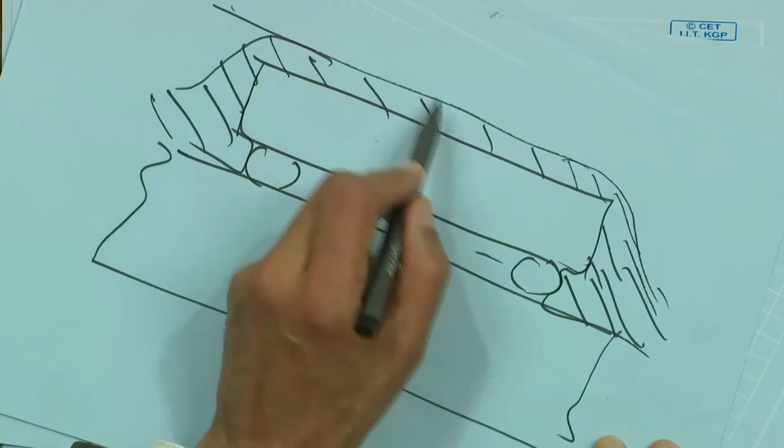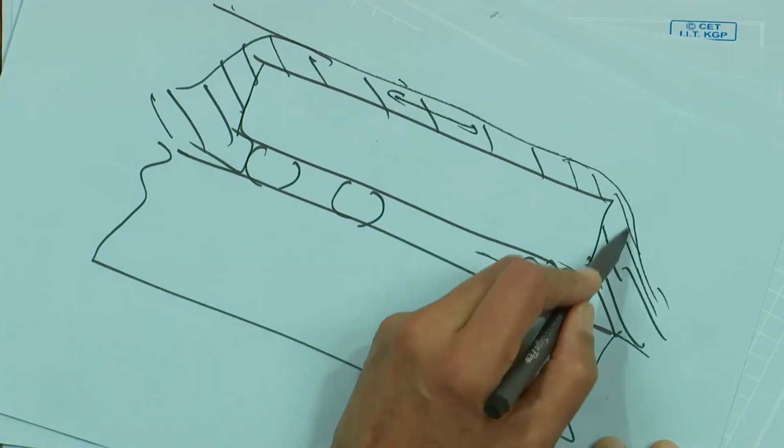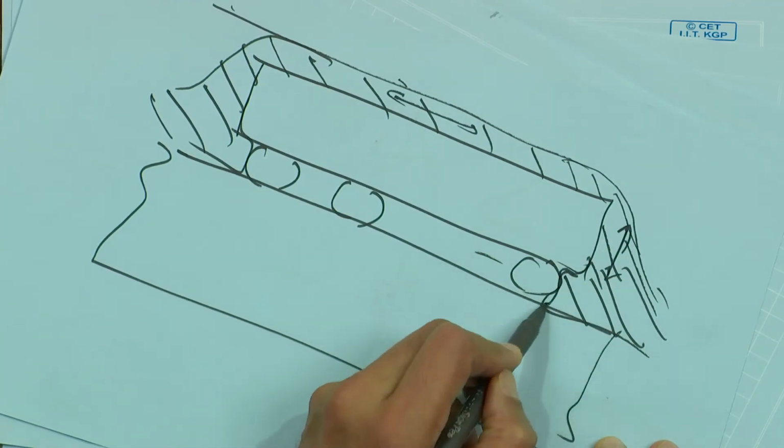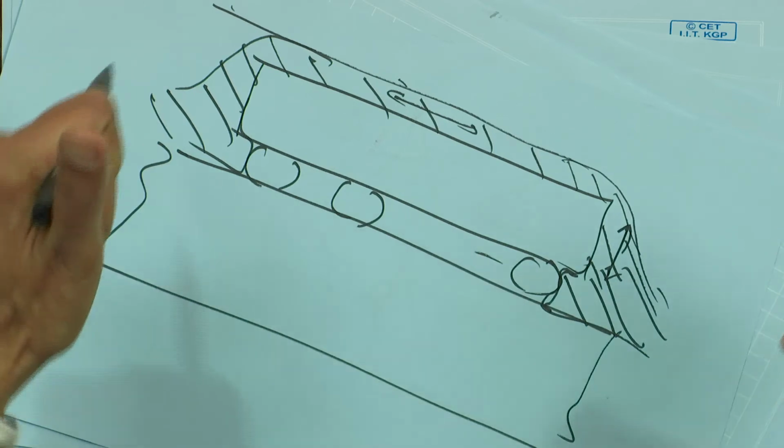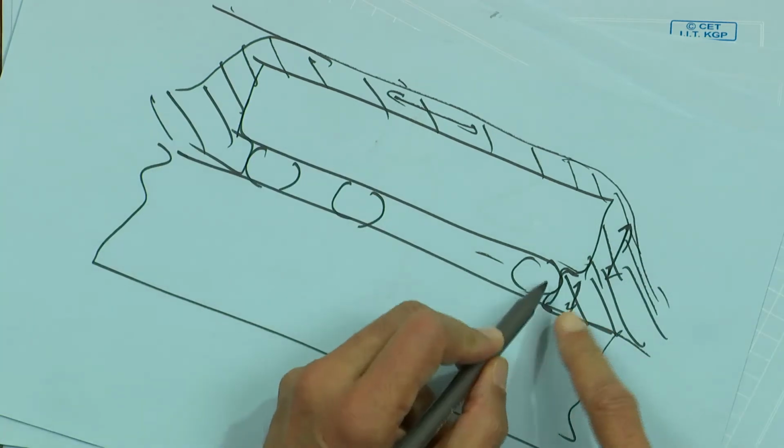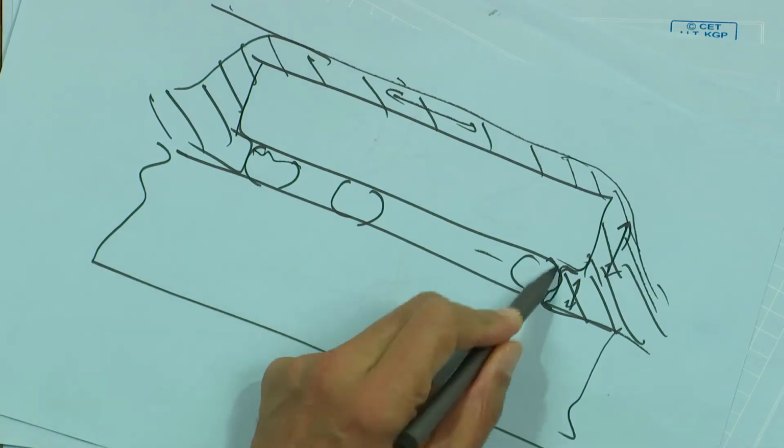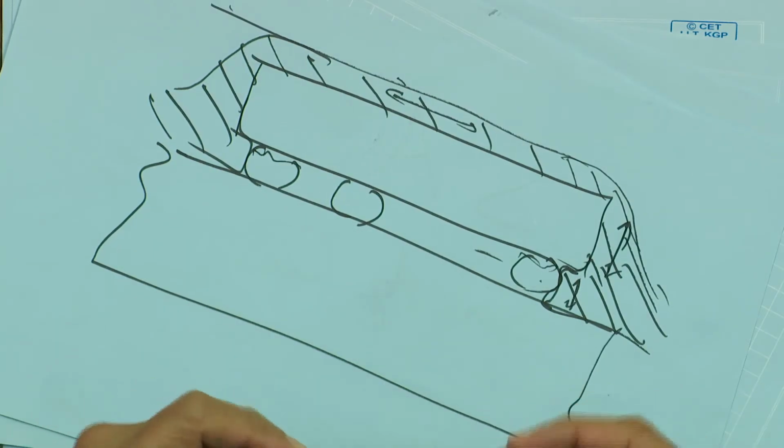Now when this expands, not only does the conformal coat expand this way, it also expands that way. The conformal coat is pushing up on the component when it expands more than solder. So now you have an unfortunate situation where with every temperature cycle, you're trying to pry open your solder joints, and they can only survive that so many hundred cycles. After a while, it fails. These solder joints start to crack, and that's the end of your assembly.